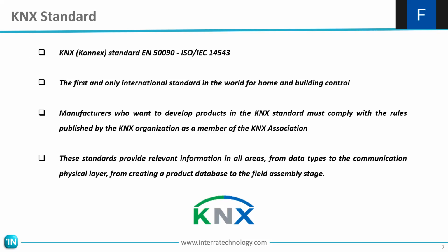KNX is an open standard for commercial and domestic building automation. It supports twisted pair, power line, IP, and RF physical transmission media, and is defined by the standard EN 50090. Konnex is a former name for KNX, but we are using KNX now. KNX is the first and only international standard in the world for home and building control.